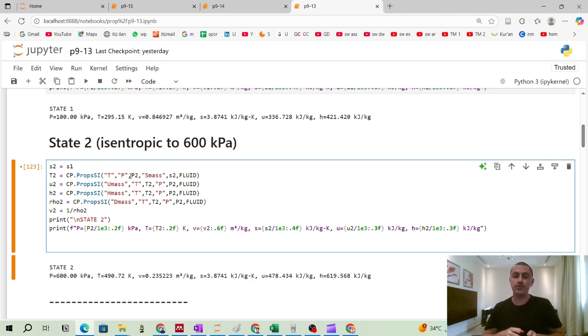So if you give entropy and pressure as an input, you cannot calculate the whole range of values. Sometimes you have a convergence problem. The solution will not converge. When I use this kind of library and do thermodynamic modeling projects, I had this problem, so I troubleshot what the problem was.